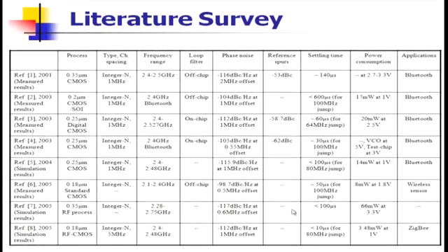If you look at here, another very important thing is the power consumption, so power consumption and the phase noise. Okay. You can always demand a very high phase noise performance, but look at the power consumption: 14 milliwatt at 1 volt, where they are getting 115.9 dBc/Hz, say at 0.25, that is also a simulation result and so on. If it is a Zigbee, 3.48 milliwatt, and that dBc/Hz. So always you find, if you scan through it, that your phase noise performance is actually a trade-off between the power consumption and the phase noise.